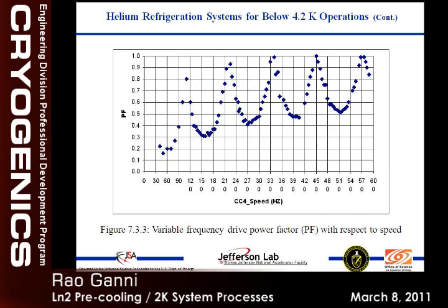And when we were talking to the folks who designed the compressor, they said they would have never thought about looking at that side of the shaft. It would have never dawned on them that it was coming from that side. They would have been continuously looking at the compressor wheel only, because traditionally the surge comes from the compressor wheel design. And because we were so sure, looking at the wheel shape and the pressure ratios where it was happening, that's where we started looking elsewhere.